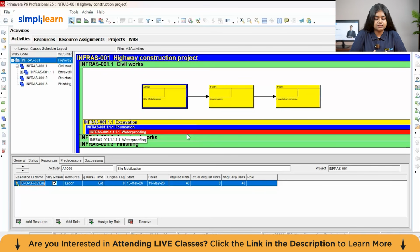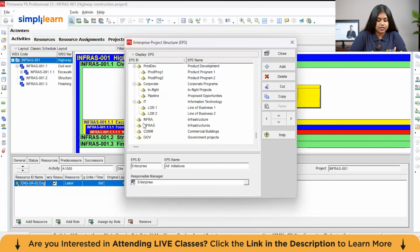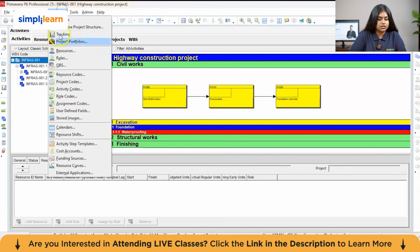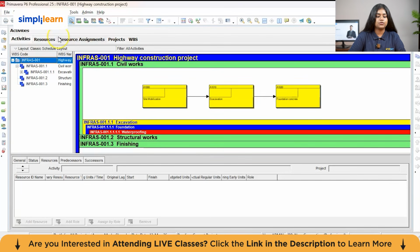The basic thing is, first we have to create an enterprise project, where we go to the enterprise section and go to EPS and create new nodes. In the new nodes, we add the projects that we want to build, such as highway construction project. This is the main heading, the main project that you have to mention in the EPS. And then we'll go to the OBS and create the organizational breakdown structure for each division, such as project control division has infrastructure and building team that we created today. So you can create as many OBS as possible for better understanding of the project.